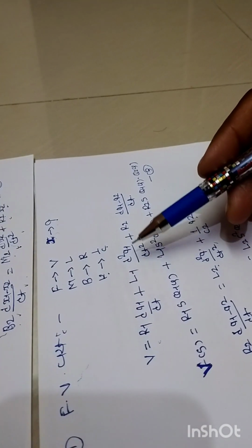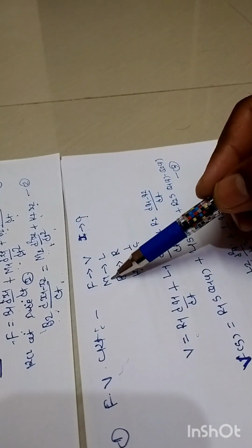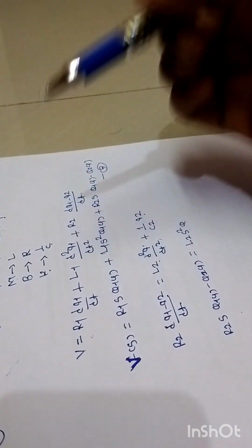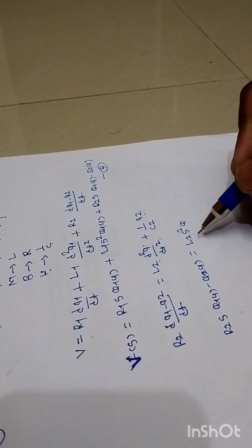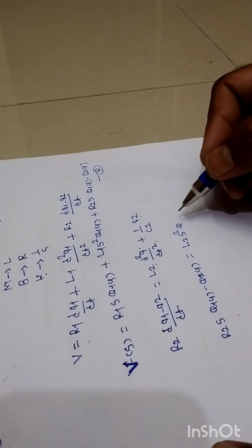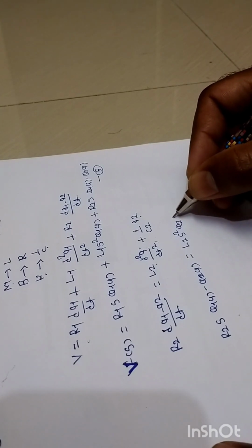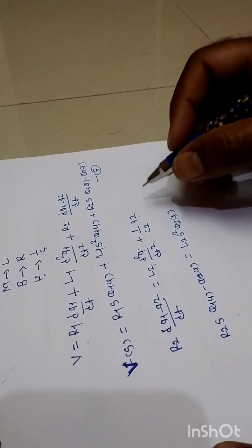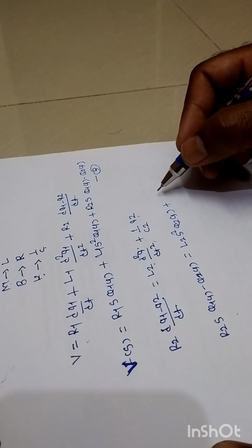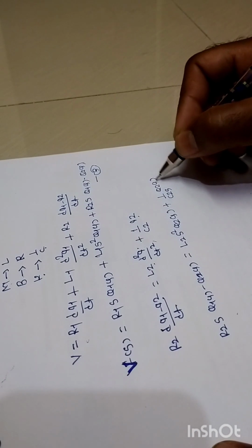So when we consider equation number 2, the mass number 2 we are having with us, this m is analogous to L. So as we are having the mass number 2, this mass number 2 is replaced by this L2, and this mass number 2 is associated with this displacement number 2 x2, which is being replaced by q2, so it will become L2 s square into q2 of s, right, plus, when we apply the Laplace transform, it will become 1 over c2s into q2 of s.